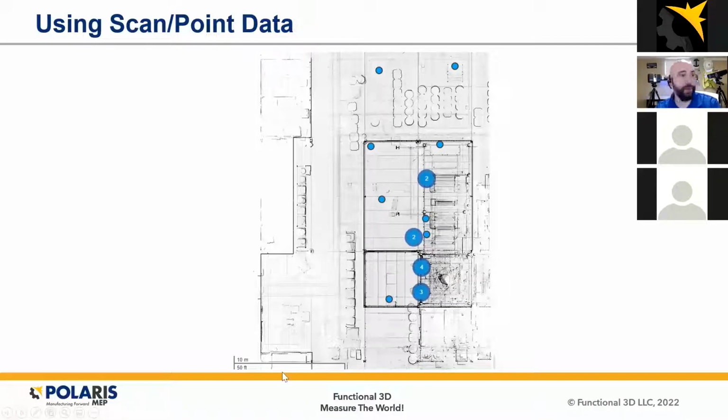It is just an image, but we can scale this image now in our CAD platform with our scale bar down at the bottom, and we could just draw right on top of these lines, and we could get our vertical beams there, our supports, we can get our walls, we can get some other horizontal beams, and get an understanding of a general layout. All right, this is some objects that are in storage. And so we can get that general layout of our facility very quickly in a 2D manner.